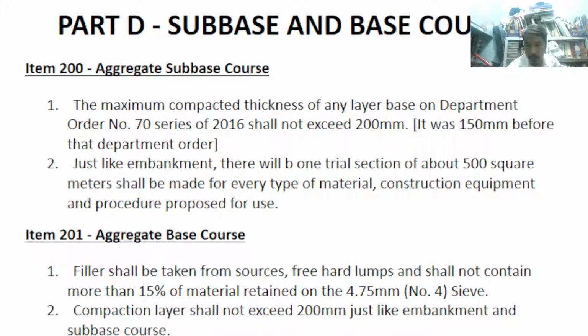So again, next. Number 2, compaction layer shall not exceed 200 mm, just like embankment and sub-base course.